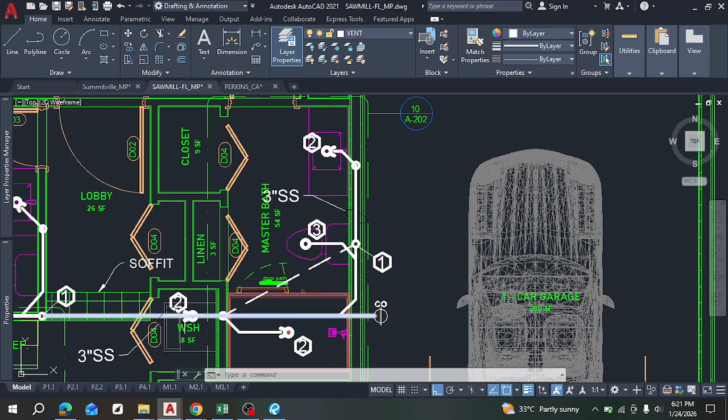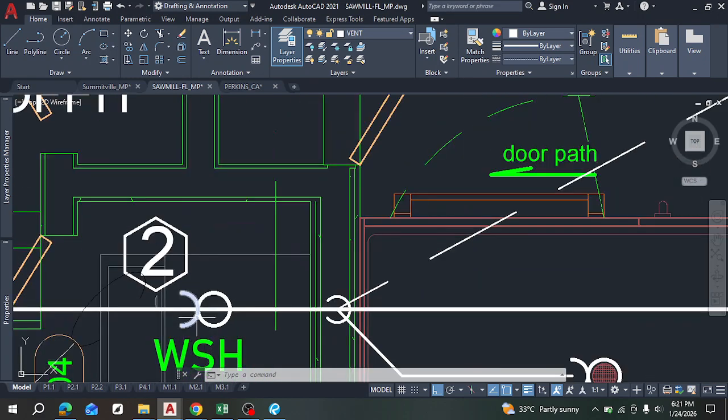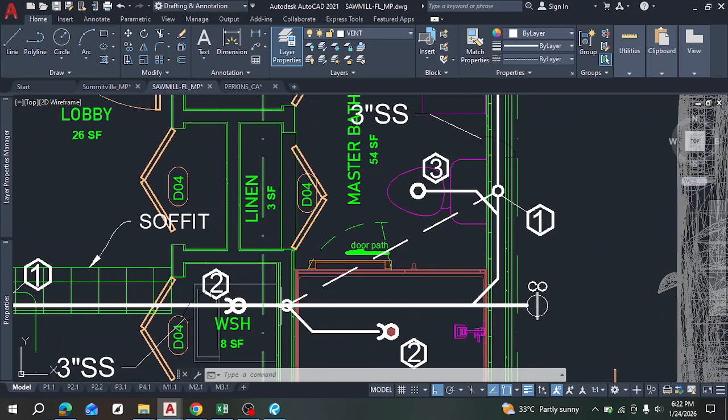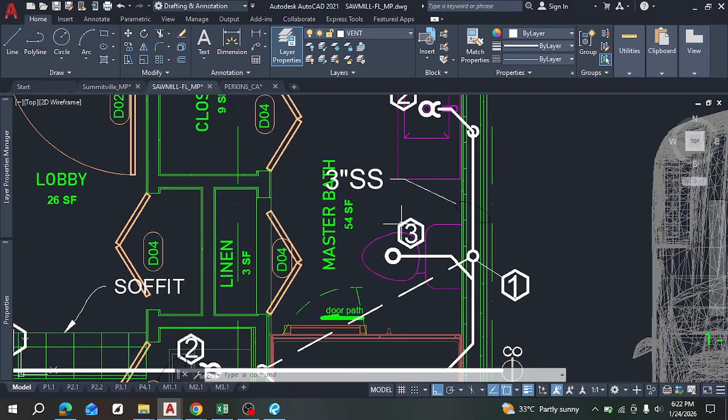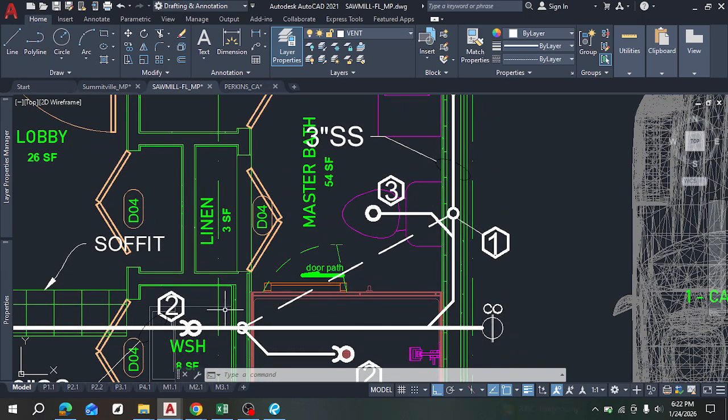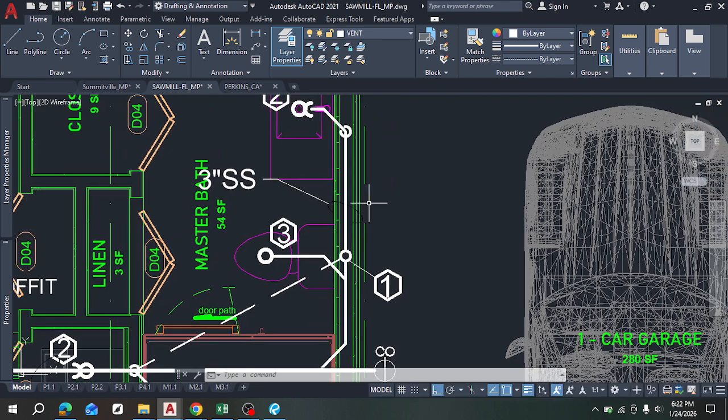Okay, these two, because this is why I made the line run here. So this just drops directly into it on the ground. So this vents this as well as this, right? So 1, 2, 3, 4, and you see that I placed this closest to the WC, for better efficiency. So all of these now are in a venting circuit that is vented up into the roof